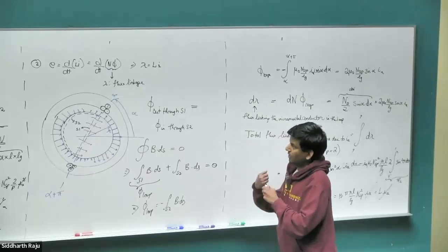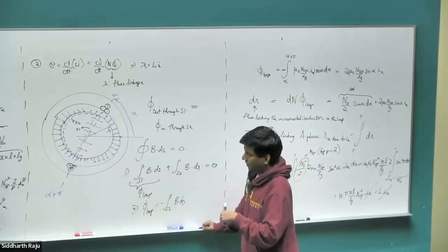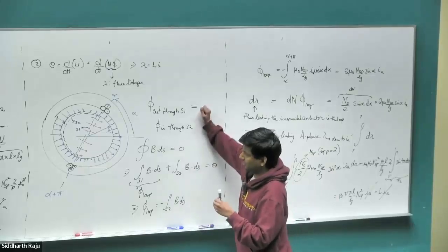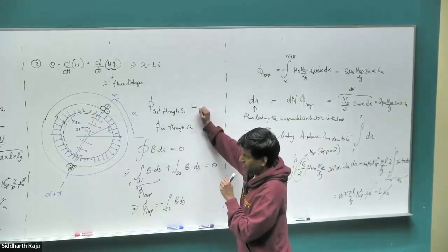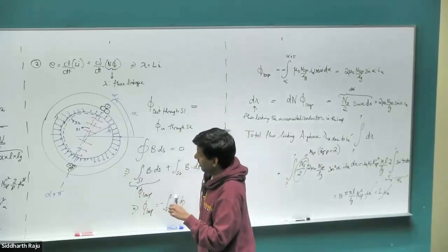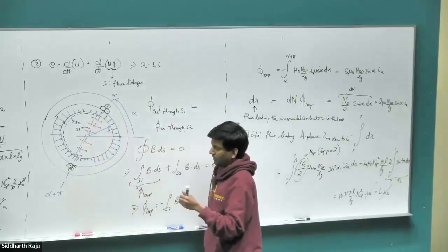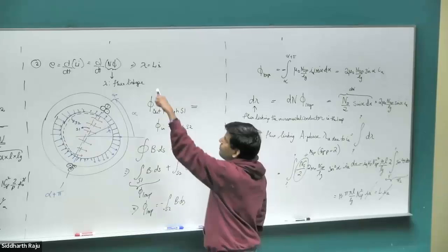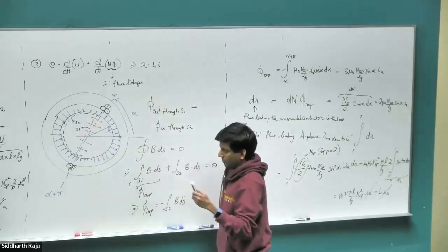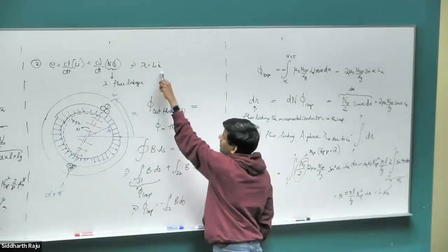Okay, so the second way of doing the same inductance derivation, this is not just to exercise our math knowledge. There is a purpose for doing this that you will see today. So the second method is we are going to look at what the flux linking all the A-phase coils is. And if we know what the flux linking it is, we know from our formula up here that lambda, which is the flux linkage that we introduced last class, is equal to the inductance times the current.